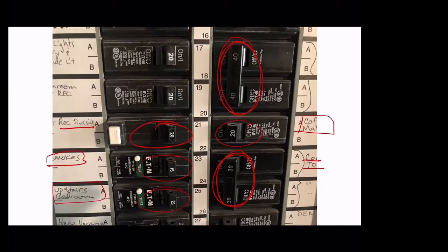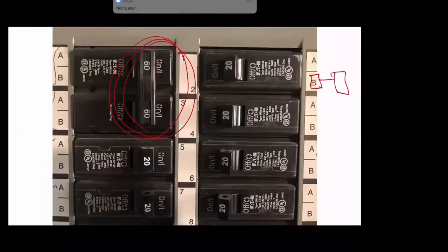And you can see this one has a GFI, ground fault interrupter, on the circuit. You can have ground fault interrupters on the electrical receptacles themselves if you're near a sink or a bathroom. But you also can have them on the whole circuit, and then you don't have to have the little buttons and ugly little receptacles. All right, and then this one actually is for a sub panel. So the one panel is going to then go out to a sub panel that's going to then go out to other things, like for an addition. And that's what happened in my house before I bought it. And then each of these others goes somewhere else.